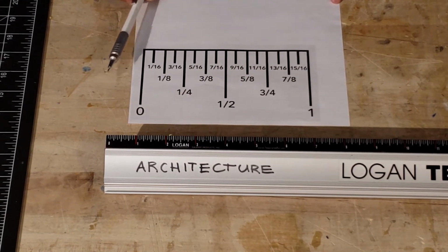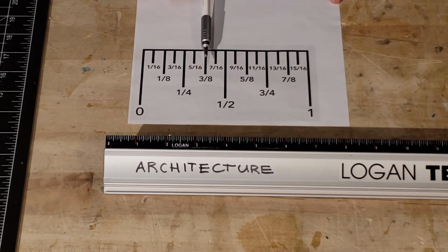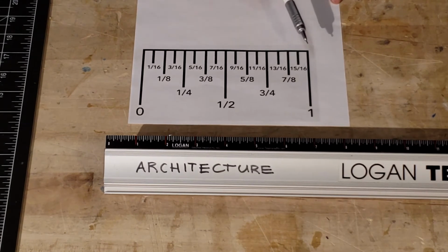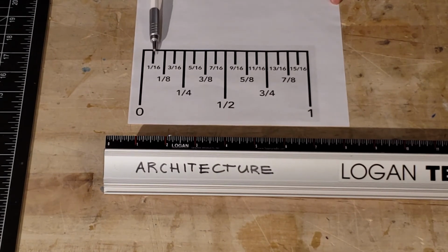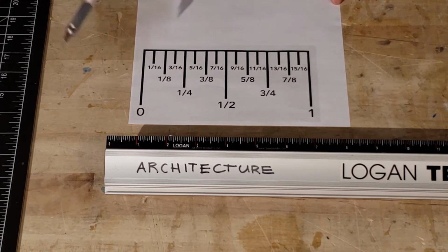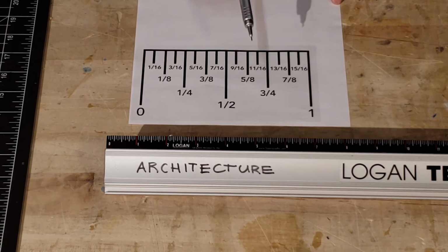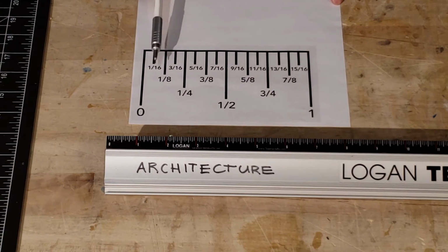You go one step further to the fourth longest line. Now the inch is divided into 8 equal parts. Then the next step would be dividing your inch into 16 equal parts. You can go one step further into 32nds, 64ths, and even 128ths. Those are used in the manufacturing process for extreme precision. However, mainly we will stick to 1/8 of an inch.